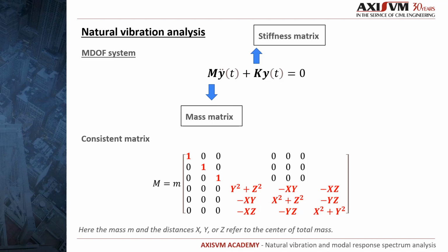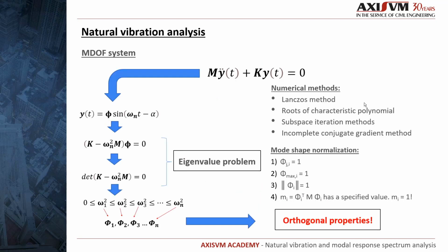On the other hand, the more complex the mass matrix is, the closer we are to the exact solution, of course. Generally, the contribution of non-diagonal members decreases with the element size, since the nodes are closer and closer to each other, and the center of gravity of the discretized system comes close to the global center of gravity. We go back to the original equation and try to find the solution using the following function.